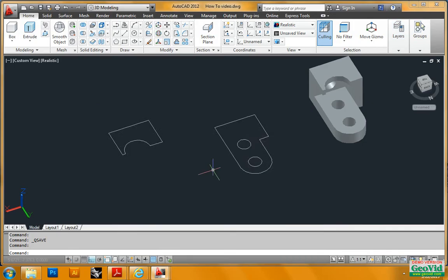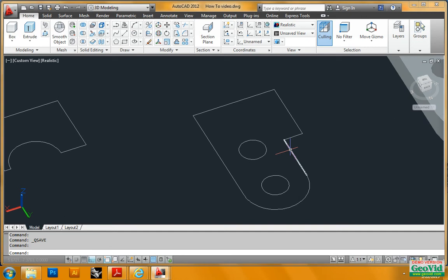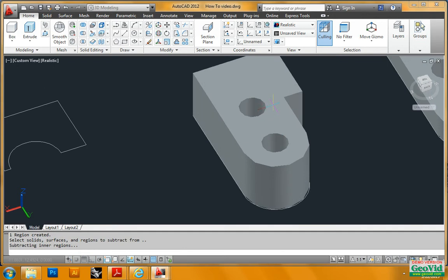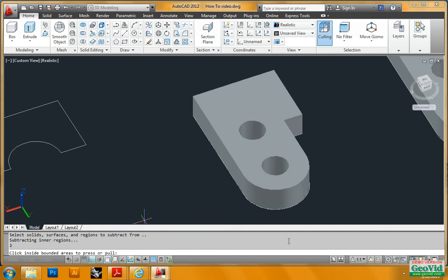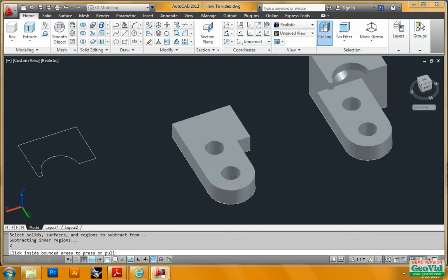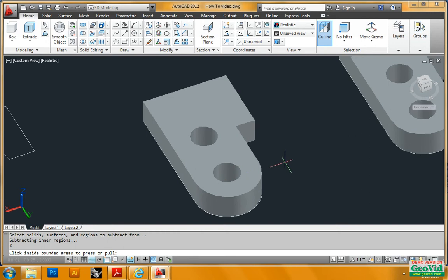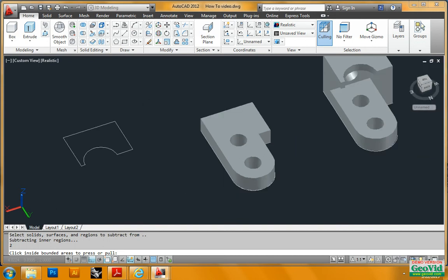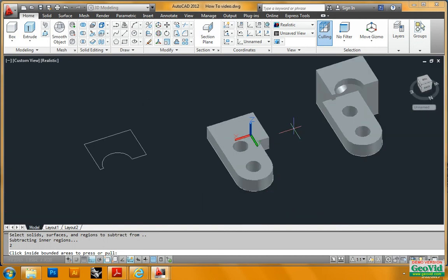So I took that and I made this, and to go ahead and start, I want to push pull, so I go up here and click in the middle of the solid part, and it's two units, so I'm going to type 2 and enter. And as you can see, because I already had the circles in place when I push pulled it, the circles stayed voided, which is very nice because then you don't have to worry about subtracting out cylinders or circles or anything like that. It's already there, so that takes a step out of your project, which is really nice when you're in a hurry.